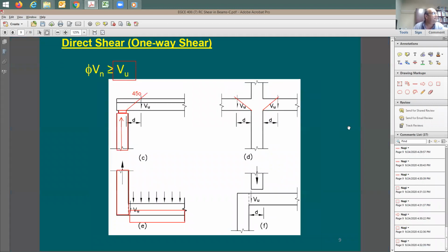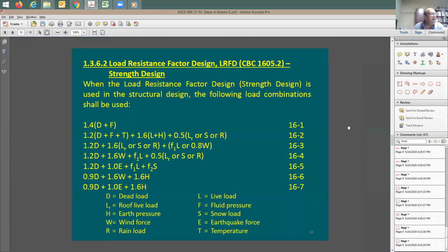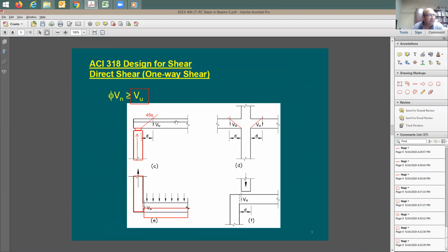All right. Now let's look here at the equation. I need to figure out the shear demand. How do you do here shear demand? Well, you need to find out the shear at this critical section. So you go here at this critical section, find out the amount of shear. Is the shear due to dead load? You can say yes. Live load? Yes. What load combinations you use?